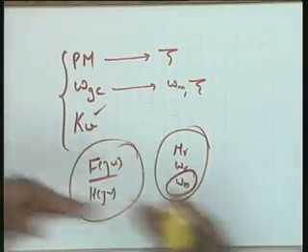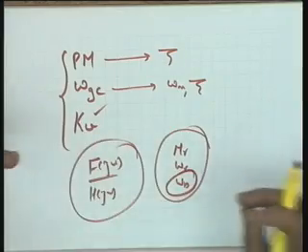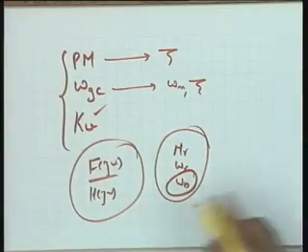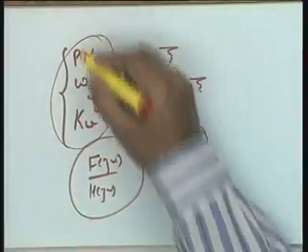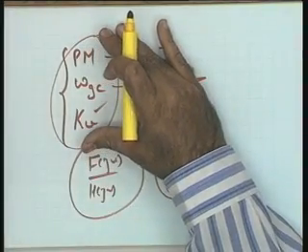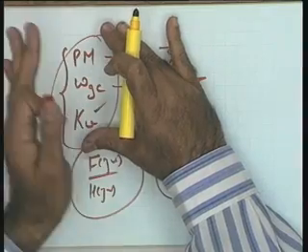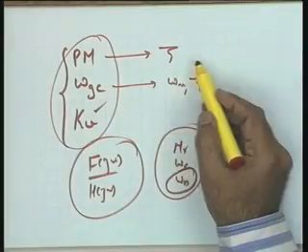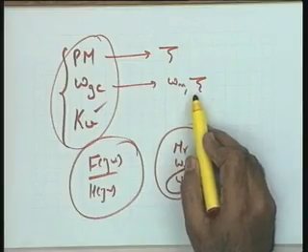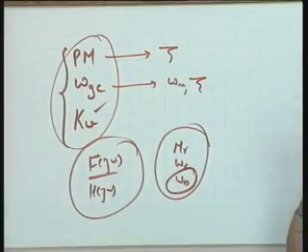I think we can have a suitable compromise between paper and pencil design and the availability of CAD. So I make the complete design and get the feel of the design from the paper and pencil work itself. The first feel of the design is available using phase margin as an index for zeta, omega gc for omega n, and Kv for the steady state error.